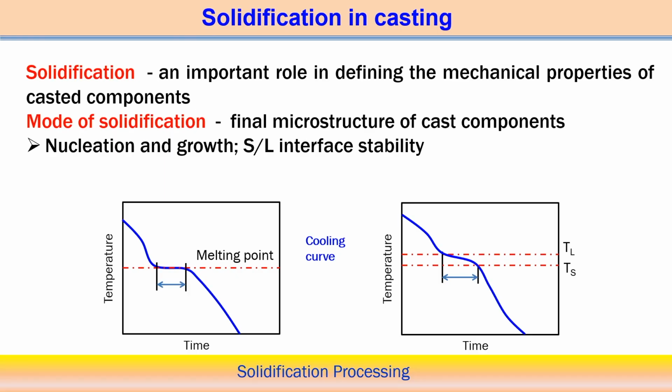In that sense, if we try to understand the final microstructure or morphology associated with solidification in the casting process, then we look into what nucleation and growth occur specific to casting processes, and what instability conditions can prevail during the movement of the solid-liquid interface in a solidification process. So, we start with the very basic things that we know, the time-temperature diagram I have shown here.